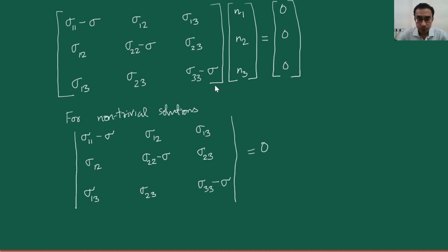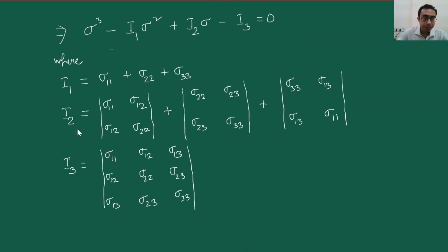We have also discussed that these are invariant values, because we understand from the physical situation that the principal stresses at a particular point is a physical truth, and it should not depend on the mathematical representation. So no matter what the individual values of the different stress components at that particular point may be, given by different values of this sigma 11, sigma 22 and sigma 33, the special combination in which they appear in each of these expressions for I1, I2 and I3 must be a very special combination, and so they must be invariants.